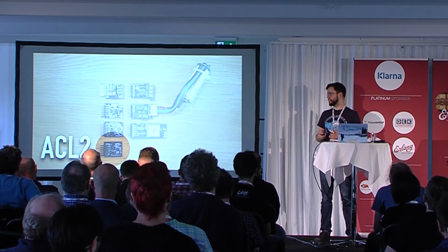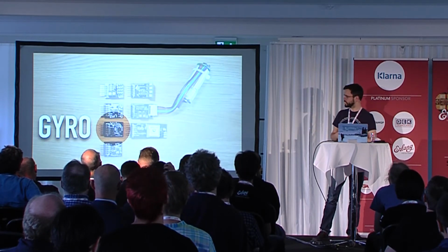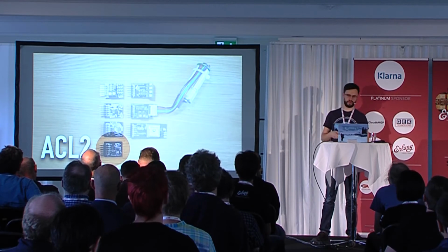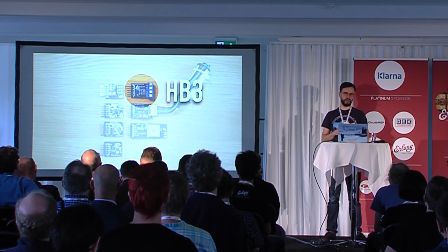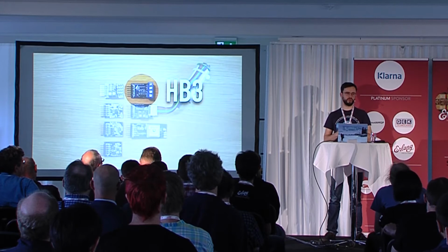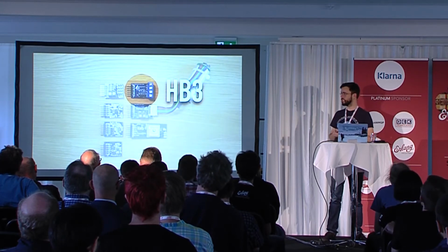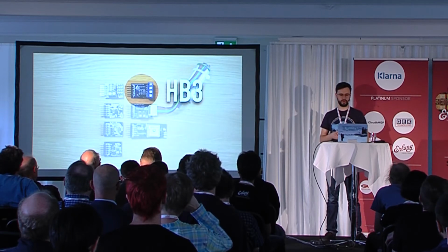And so this new one is the cool one because it has all in one kind of, but you can also buy them separately. And I'm gonna demo this one later. HB3 is an H-bridge driver, so you have feedback inputs. So you can drive a DC motor with up to 12 volts. So you plug in the motor and some external power to this, and you can actually drive a motor.